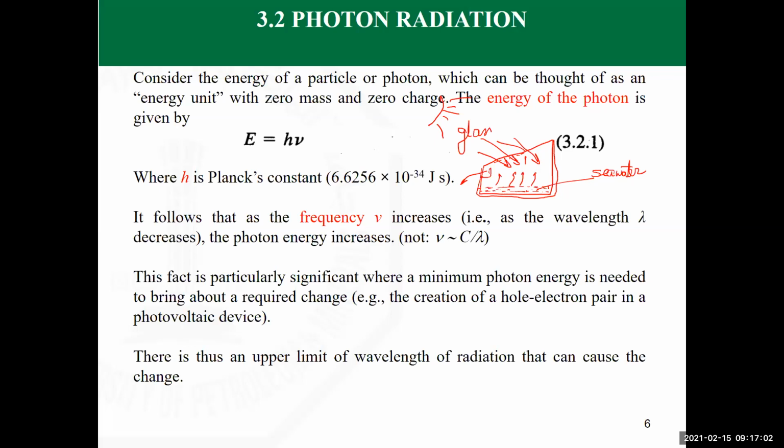And on the top you have a sheet of glass or maybe polyurethane. You can put it on the top and then you have your own system to create fresh water. So this is one of the applications where thermal radiation contributes a lot by just understanding the concept of greenhouse effect. Definitely, this is all tight. We don't allow air to come in at all so that the temperature remains higher than the surroundings.